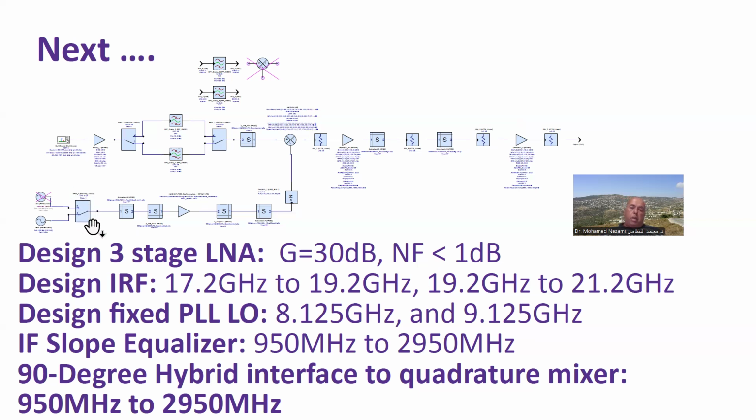I designed one Ku band system where I didn't use switches in here, but what I did use is turning these on and off, okay? And they were basically combined with a two-way splitter in here, just to maintain impedance matching, okay? Just like I would do here, I disable this, meaning turn this off, turn this on. Okay, so we need to design that.